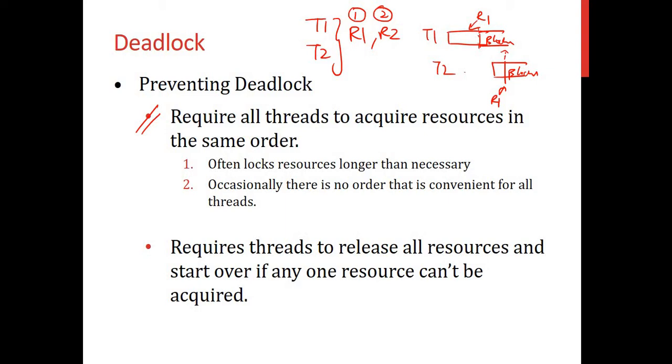So effectively, if I enforce the order, whoever is the first person to lock the first resource will ensure that he will eventually get all the resources subsequently, one after another, until he finishes everything and releases the resources. So by enforcing the order in which resources are acquired, I can ensure that deadlocks will not happen, because any other task that also wants these shared resources will have to wait until the first task that acquired the first resource releases everything.